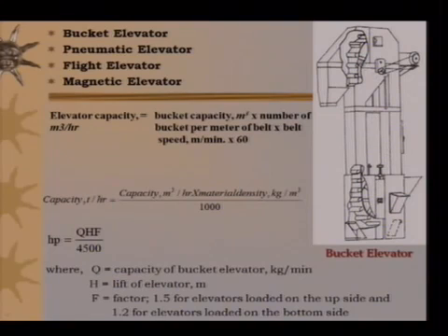As the pulleys operate, the belt, which is normally made of rubber or canvas, operates, and the buckets also go along with it. They pick up the feed from the dump where the material is dumped, granular material, normally grains, and they can discharge it at this end here.